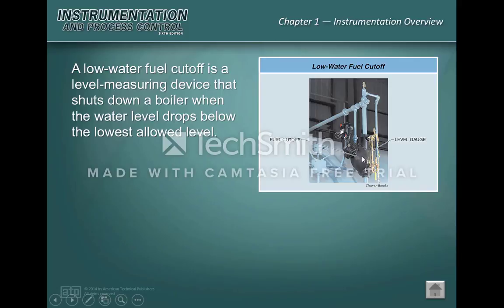Inside this, if the fuel drops, or if the water drops below a certain level, there's a mechanical switch in there that will close, and it will cut the fuel, most notably propane, off to the boiler, and the boiler will shut down because then there's not enough water in here. And if you pour hot water on, or cold water on hot steel, it expands very, very fast. So if you do that in a huge boiler, you're going to blow up.